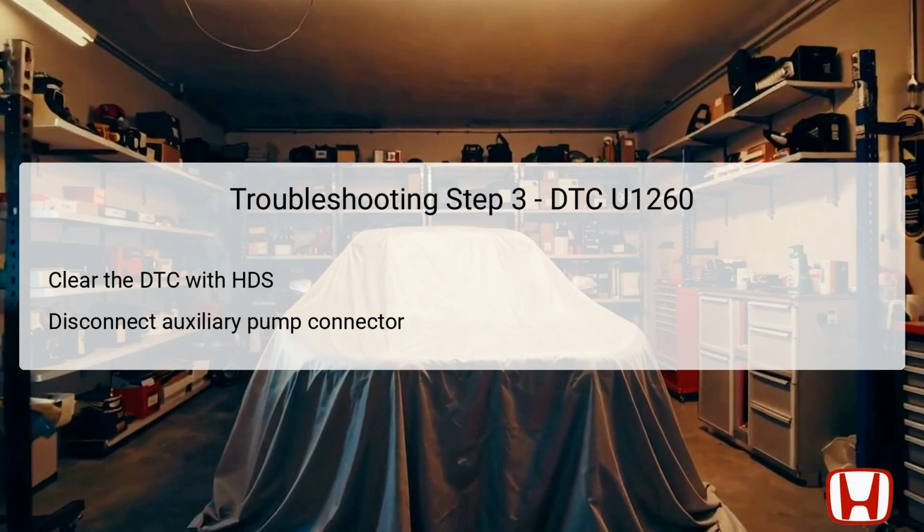Here, you will measure the voltage between specific test points in the disconnected state to determine if battery voltage is being present at those terminals. If voltage is detected at test points 1 and 2, you can conclude a potential issue is not within the power supply circuit itself, hence escalating to the next troubleshooting phase.